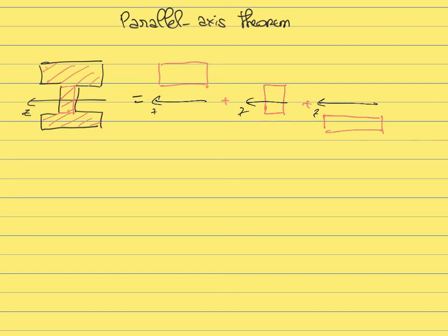So we're going to see the expression, but there's different ways that you can decompose a given surface. For example, if you take the same I-beam again, another way to decompose this I-beam, which actually probably would be even better, is that if you have this I-beam like this and you would calculate the moment of inertia about Z, you could say that this I-beam is equal to a big surface like this, a big rectangle like this, from which you would remove those two rectangles.